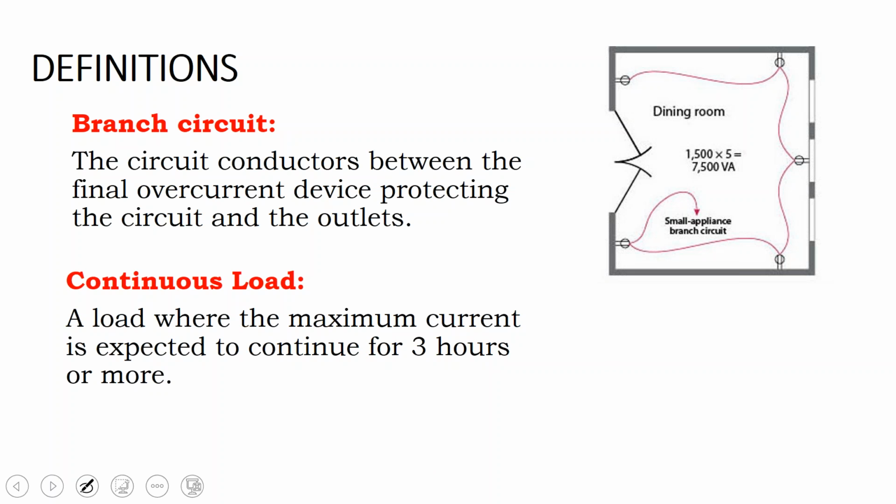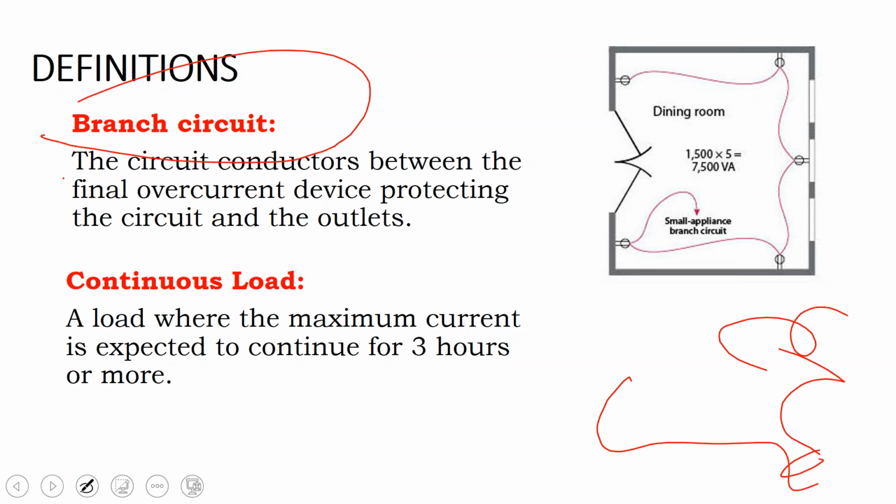Well, then we get into regular electrical stuff. We have branch circuits. Branch circuits are our lighting circuits and our ceiling fans and stuff like that. And we talk about how in the DC realm, we call our DC circuits strings, and that's really just to differentiate an AC branch circuit from a DC branch circuit. The industry jargon is to say strings for DC circuits and leave AC circuits being branch circuits. But you really could have DC branch circuits too if you're being technical and not using the industry jargon. We have continuous loads, and this is where you have continuous loads and you have non-continuous loads.